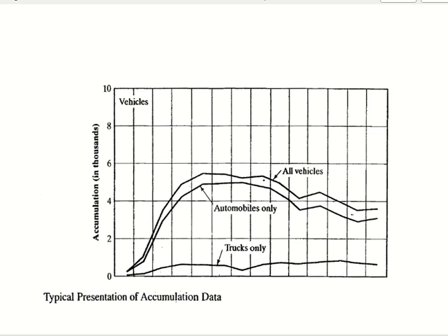In some of the areas, the congestion or the problem is because of heavy vehicles. If you go towards port, for example, in the port area, the problem is because of trucks. If you go towards the education area, the problem is because of buses. So then you do the separate counting so you can see when is the peak time for trucks and when is the peak time for cars. You may do some planning for them separately. Got it?